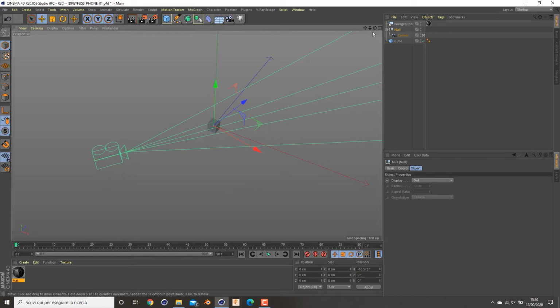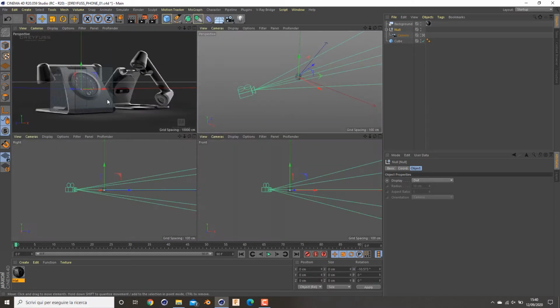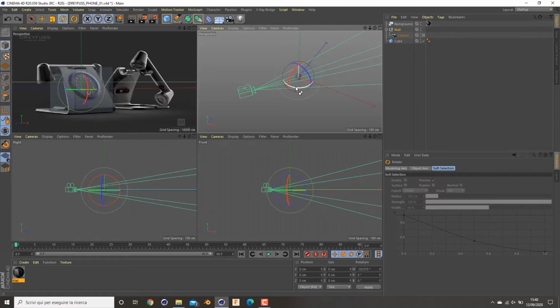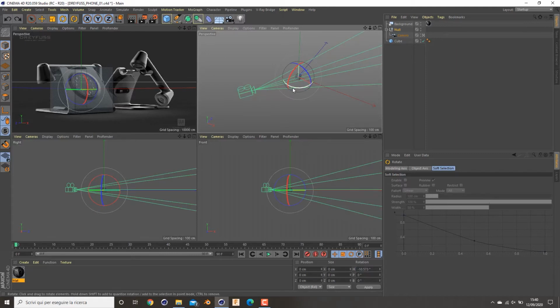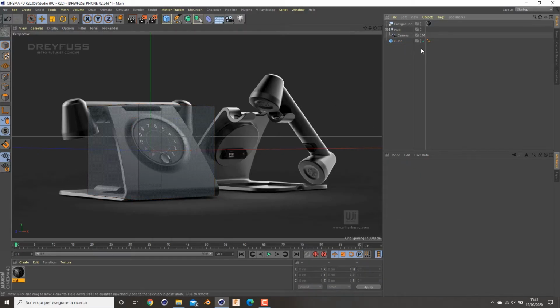I have also created a background object in Cinema 4D, and applied my image on it to create my reference for modeling. I have also linked my camera with a null, positioned at the center of my cube, to create a simple rig, so when I rotate my camera the center of my view is still on the cube, and I don't have a problem resetting the cube in the right position in my scene. Okay, time for modeling now.